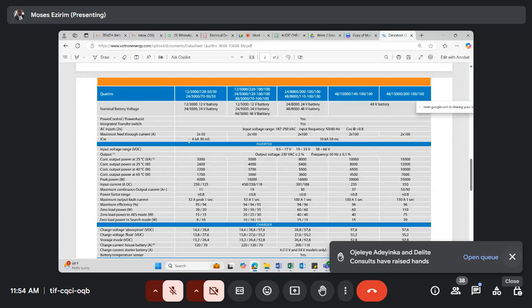So in this case, your PV should be sized in such a way that you should be able to get the addition of these during the day. Remember, PV is usually sized in kilowatt peak. But at the end of the day, you should know what the energy will be. What is the energy? It is just multiplying. For example, you installed 10 kilowatt peak. To know the energy, just multiply with the peak sun hour. If the peak sun hour is 3.95, once you multiply, you get the energy.